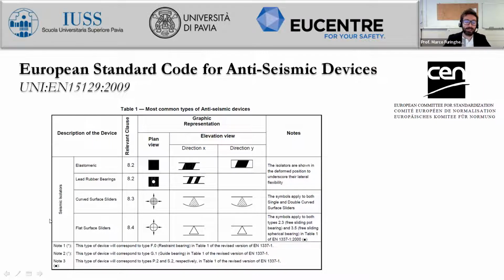Okay, this is listed as a seismic isolator, but generally it is not properly considered a seismic isolation device. We saw yesterday the main goals of isolation devices. One of them, the last which was listed, is the recentering capability of the device, something within the device which provides a force response that leads the structure towards the zero displacement configuration. And for the flat slider, we don't have anything of that.